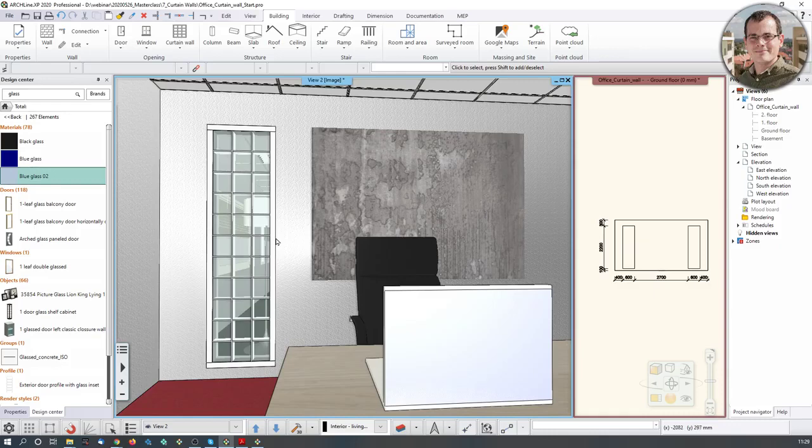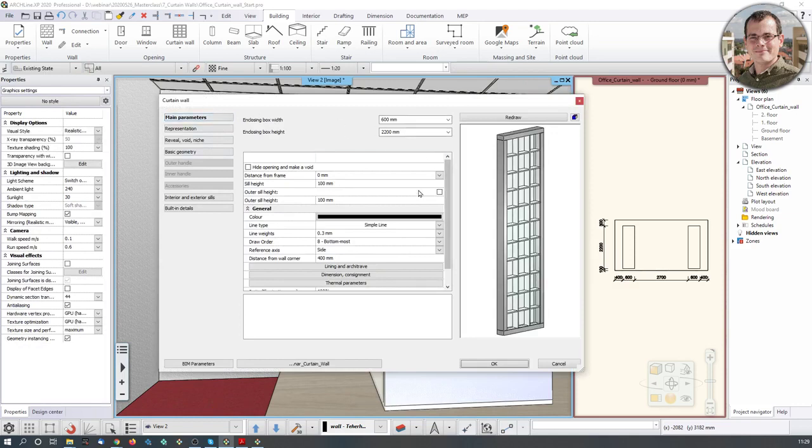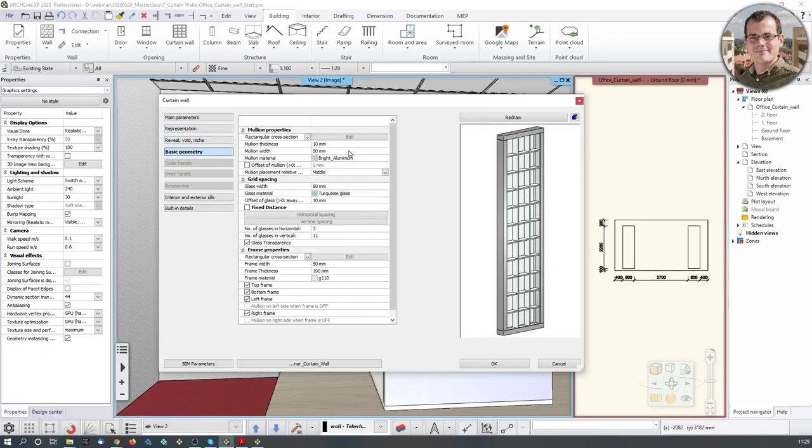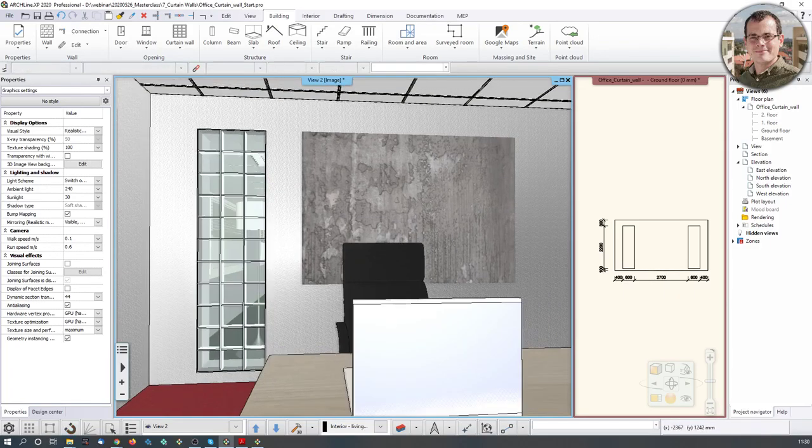Let's just go back to the drawing and say that this I have to change, and the frame thickness should be. Let's just see where I can actually find that. I think it should be frame, and in the beginning I did show you where to change that. I think that was the one. The thickness, yes, here we go. So 10 millimeters instead. Let's just change it to 100. And later on I'm going to look this up where you can actually fine tune that. Oh, here we go. So that's what I wanted to achieve. Okay, hit OK. And now I have the right result.